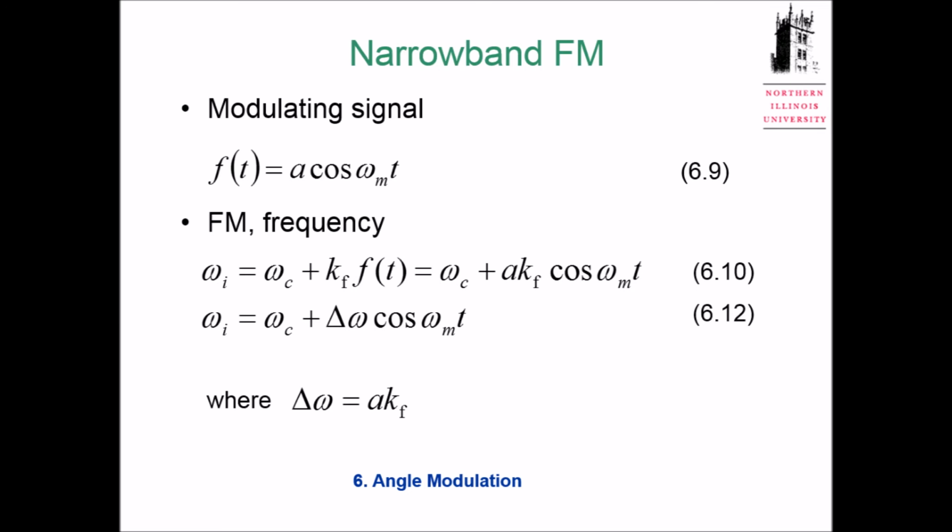Okay, here is an example. This is a picture from our textbook. For two different signals, we have PM, FM, PM, FM. FM is easier to distinguish because higher amplitude is always associated with higher frequency. The other one will be PM. If you really want to tell PM, your frequency is associated with the changing of your message.